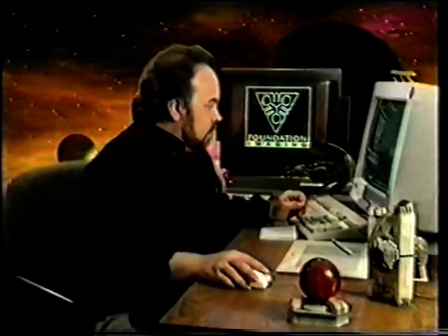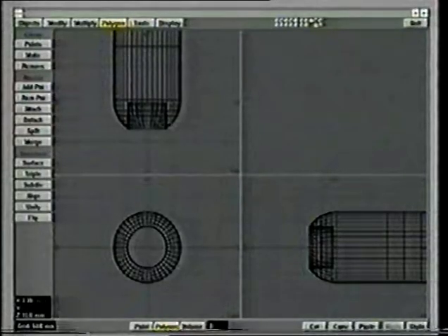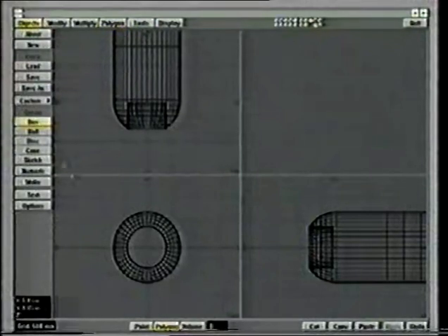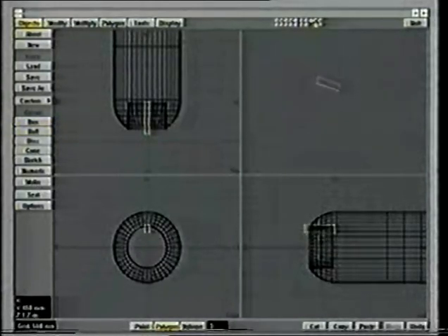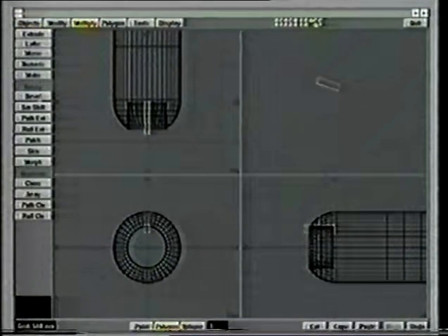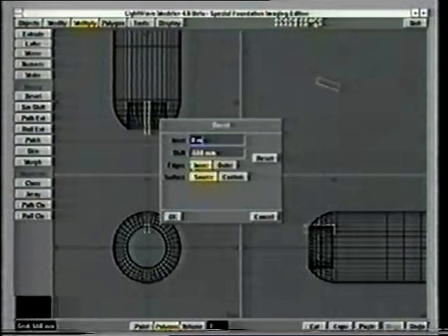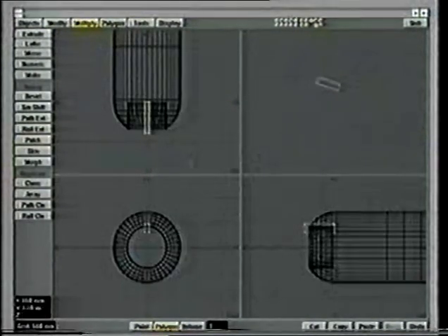Now, here's where it's going to show up that it's very, very handy to keep these objects on the 0 axis whilst you're building them. We're going to make a little radial detail around the edge here. So, objects box. Let's bring that out to there and make that. I'm just going to select the outer polygon of this box and do a little bevel on it. Inset of 10 millimeters and a shift of 20 millimeters. That looks fine.